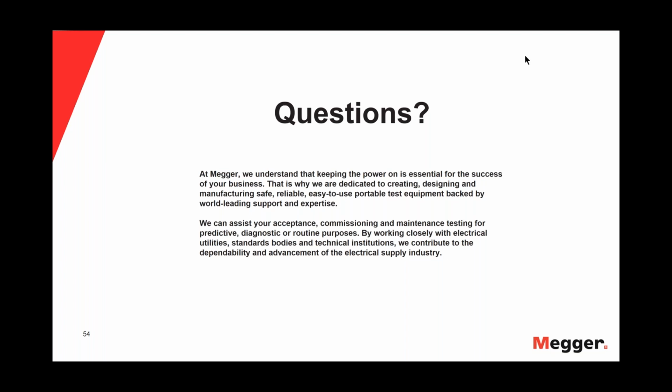And by the way, that is the same issue that you sometimes have on tape shield cable with doing PD measurements, because in the end, it works the same way, or similar in nature. It is not the radar and the tape shield, it is what happens to the tape shield when it ages. And you never know how badly it's aged.